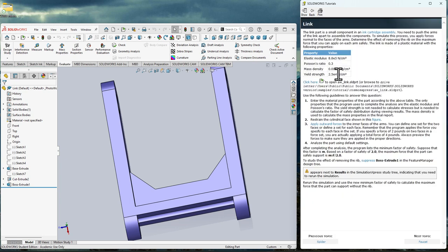So it wants us to assign this property stuff to it, and if you look, they're dirty and mean because they put it in centimeters squared, so we need to make sure we convert units here. I think ultimately we just multiply this times a million to get it to Newton meters, if I remember right. Oh no, this one's times a million. This one's times 100 squared. So 100,000. Right? No, 10,000. All right, and then this one is just a ratio, so it doesn't matter. There's a unit list there. And then I think that was it on here.